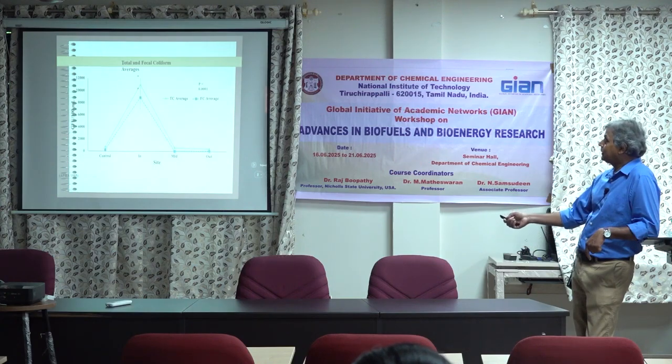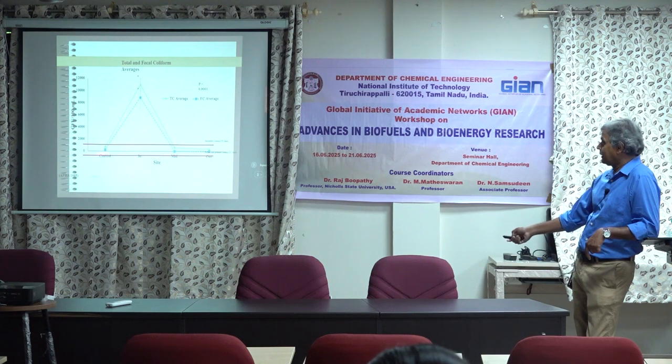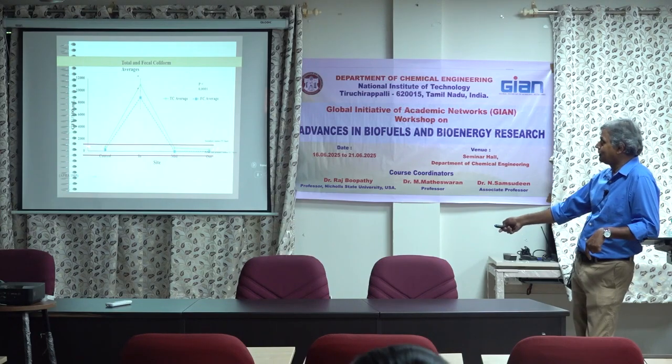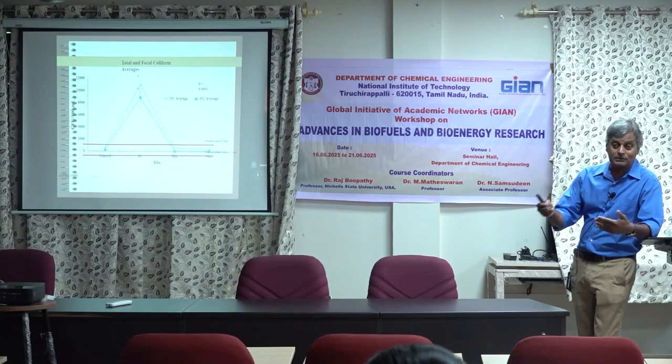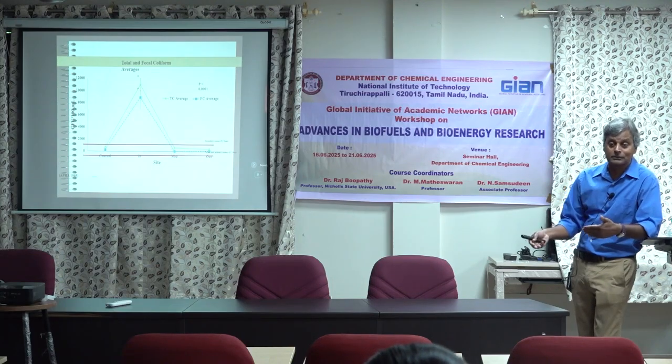And then we measured the bacteria we call total coliform, fecal coliform indicator organisms. You can see the control site, inside, mid-site, outside. You can see the inside has a lot of fecal coliform, outside has no fecal coliform compared to control, same data. So what's happening is the algae are filtering them out, and that's really good for the natural system.